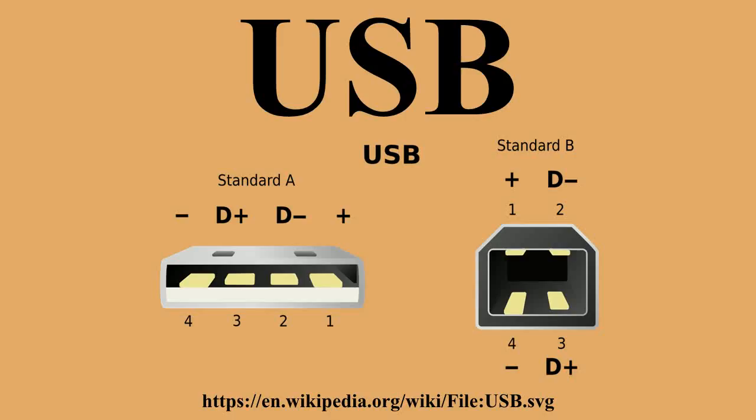USB On-The-Go makes it possible for two USB devices to communicate with each other without requiring a separate USB host. In practice, one of the USB devices acts as a host for the other device. Battery Charging Specification 1.1, released in March 2007 and updated on 15 April 2009, adds support for dedicated chargers, host chargers and no-dead-battery provision, which allows devices to temporarily draw 100 mA current after they have been attached.